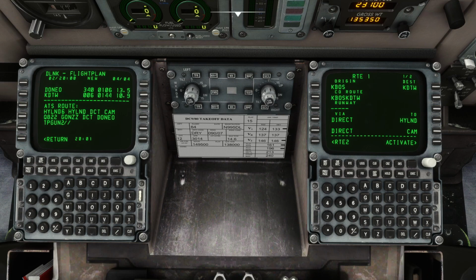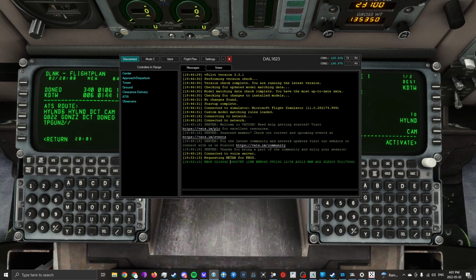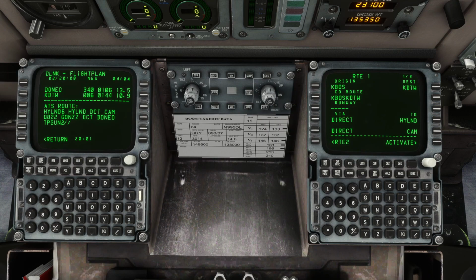Now, for runway for departure, I'll finish reading the METAR here, which I'll bring up to you. The winds are 090 at 7 knots, 10 statute miles, broken 6,500, overcast 15,000, temperature 12, altimeter 3. So it's not icing conditions. With the winds 090 at 7, that would make, let's see here, that would make runway 9 right. I don't think they usually use that for departures though, unless it's a high traffic situation. So I think we'll just take runway 04 left in that case.